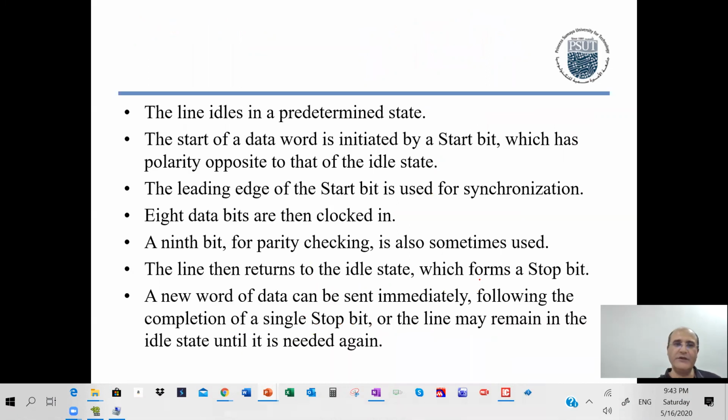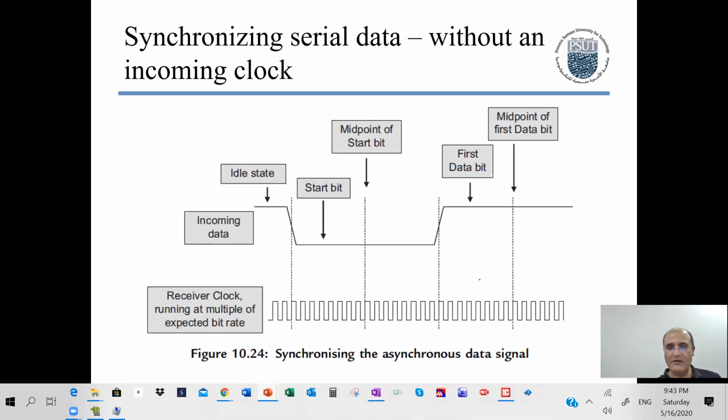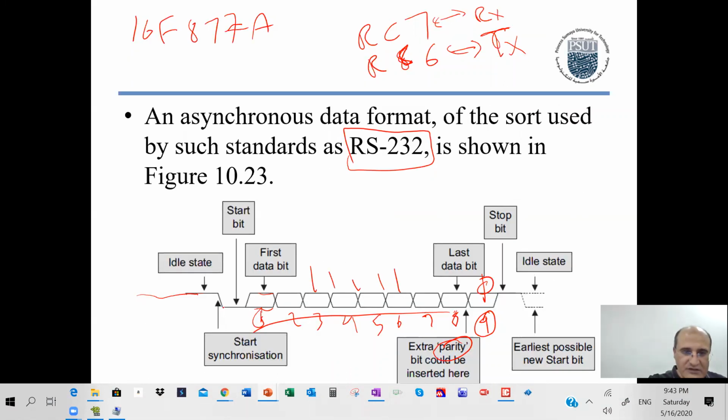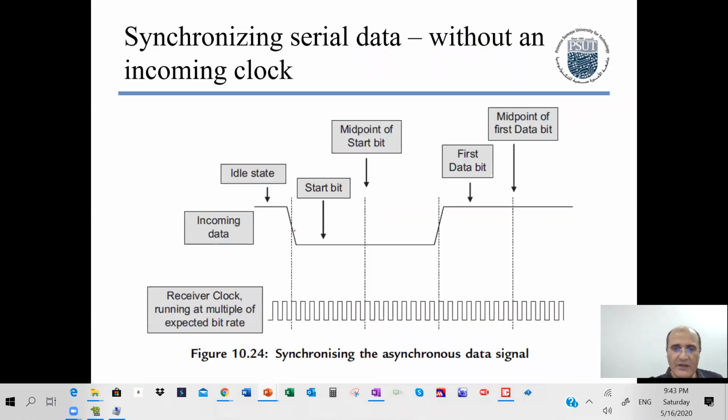This describes what we said right now. The timing: this start bit, first bit, second bit, third bit, each stays on the line for a certain amount of time, which is several clocks. Here this is a zoom in. This is the receiver clock generator, and the transmitter has another clock, and this could vary from 10 to 20 clock pulses.